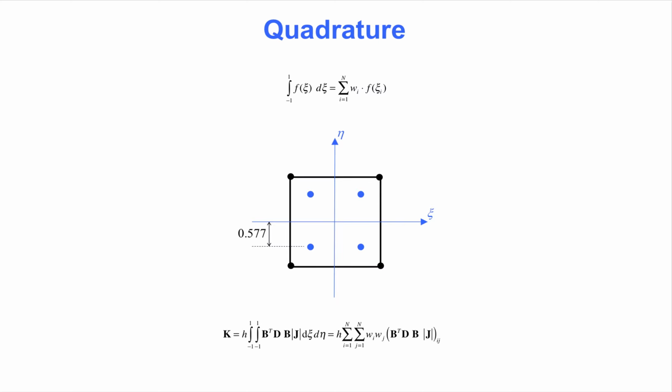On the other hand, the quadrature order must not be so low that the volume of the element is incorrectly computed. This has to do with retaining the convergence properties of the element. The element must be able to capture the constant strain state exactly. Reduced integration may also cause unwanted mechanisms. A mechanism is a deformation mode associated with zero stiffness.